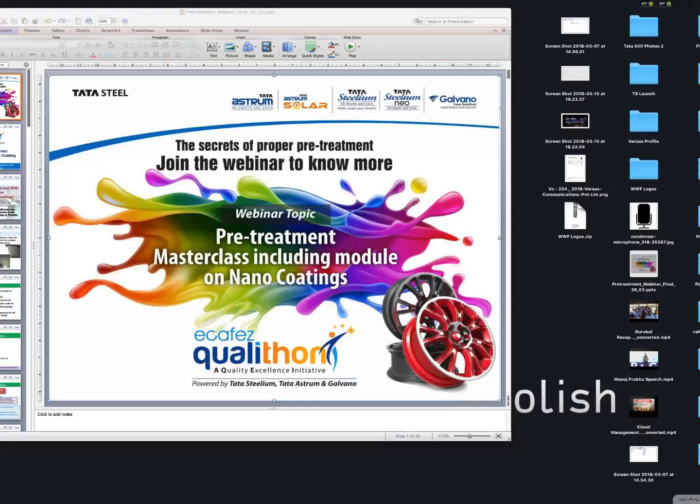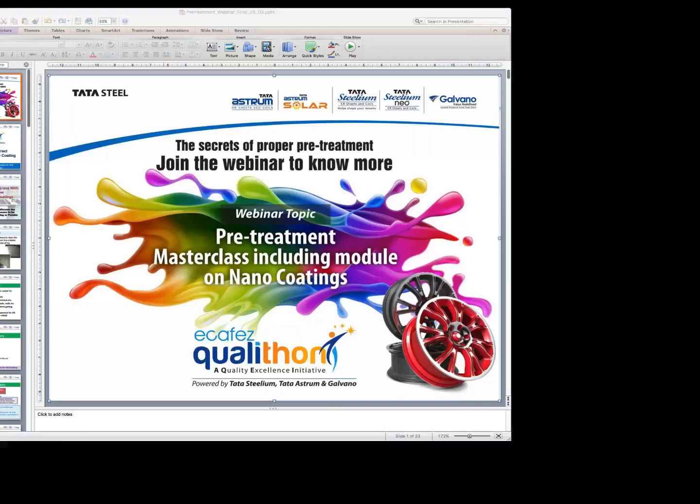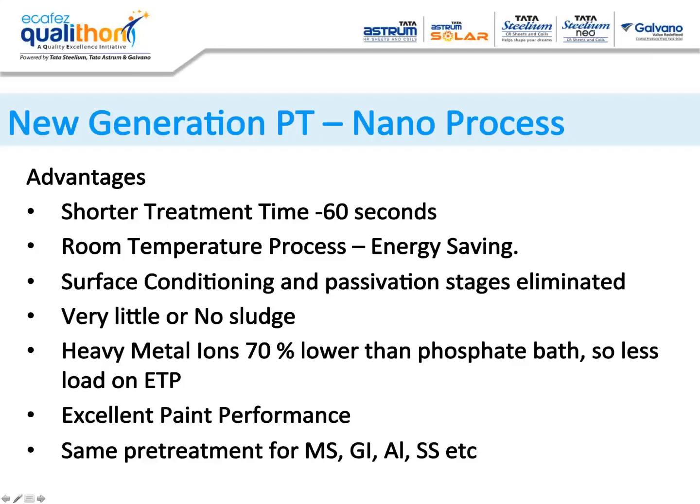Mr. Sudhakar Pokarkar, does the alkali resistance of paint depend on the phosphate coating quality? Not really. For example, if you have a good epoxy paint, that will have very good alkali resistance. But if your pre-treatment is not very good, any coating is going to fail for anything else. So ideally, you should have a good pre-treatment so that all these resistances work very well.